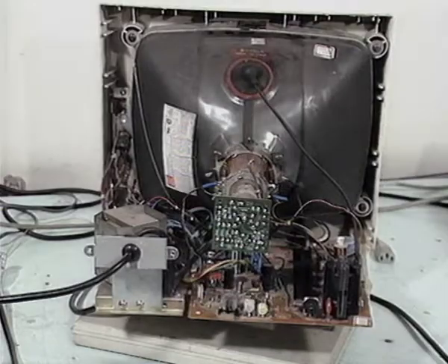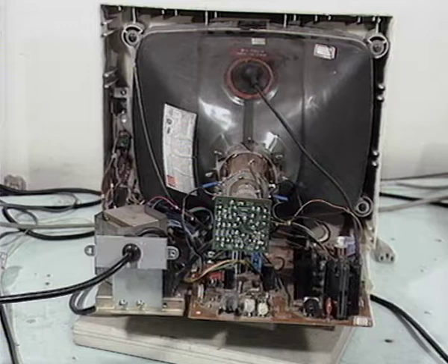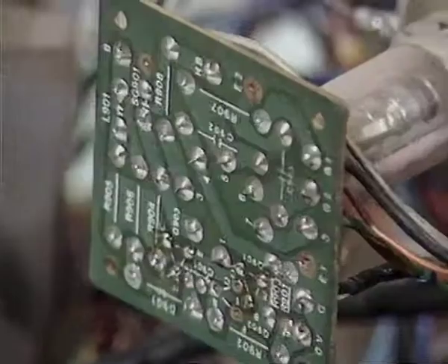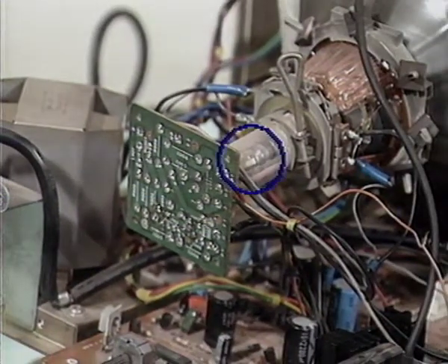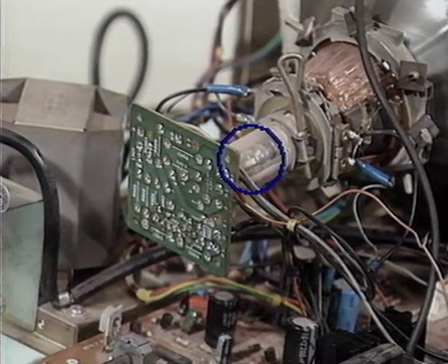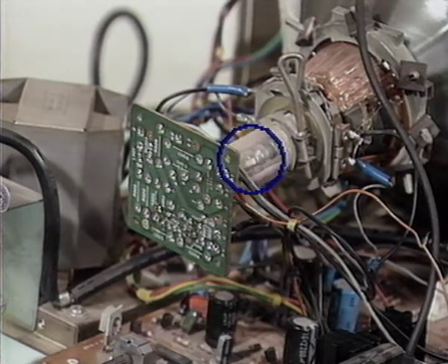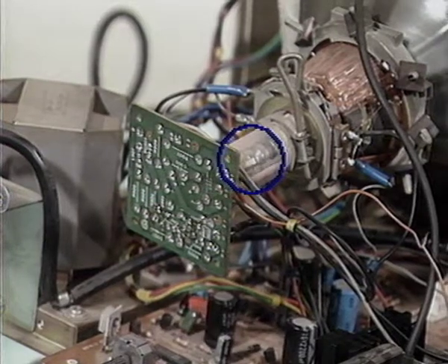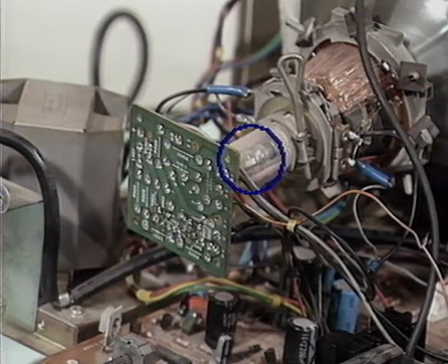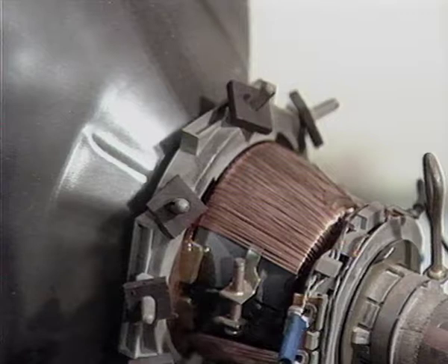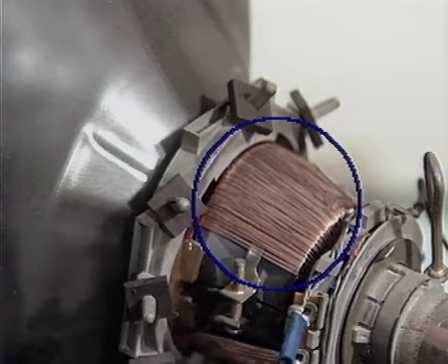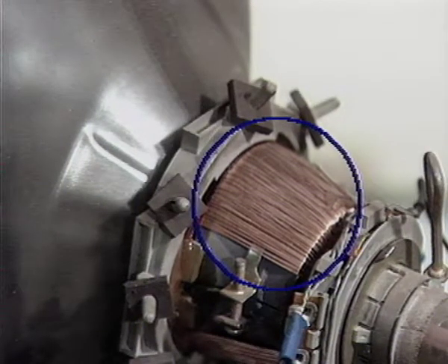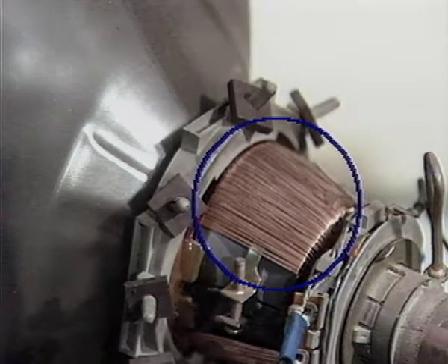It has three parts. Number 1, an electron gun for producing a narrow beam of high-speed electrons, which is also known as the cathode ray, in an evacuated glass tube. Number 2, a beam deflection system, which can be electrostatic or magnetic. And number 3, a fluorescent screen at the end of the tube, which emits light where the beam falls on it.